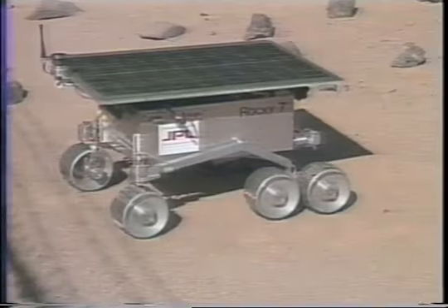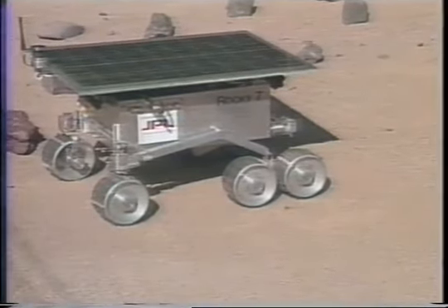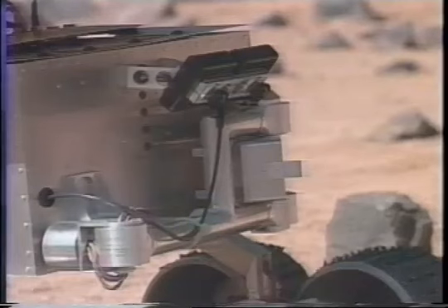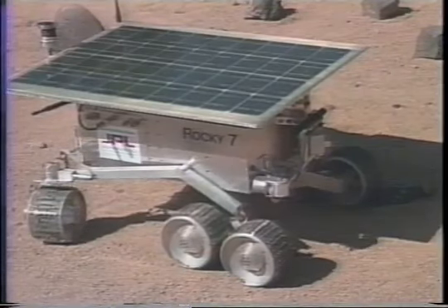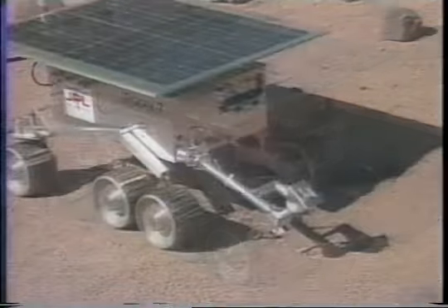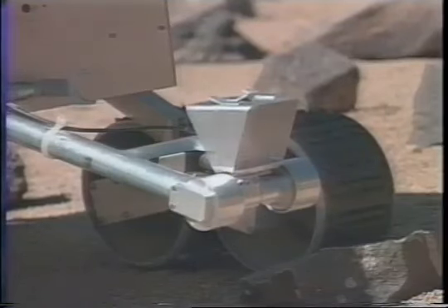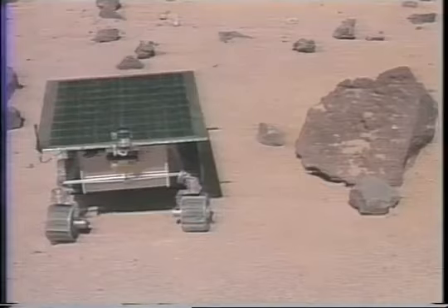The rover receives the command sequence and begins moving to the first waypoint. The rover performs obstacle detection using images from its front cameras and alters its path if necessary to avoid an obstacle. When the rover arrives at the first science target, it executes a goal ID subtask to confirm the target, and then executes a spectrometer read command. The rover automatically adjusts its position to prevent any collision with the rock. The rover deploys a calibration target for the spectrometer, and then takes spectrometer readings through an opening in the front of the arm. The rover then traverses through waypoints to the next science target.